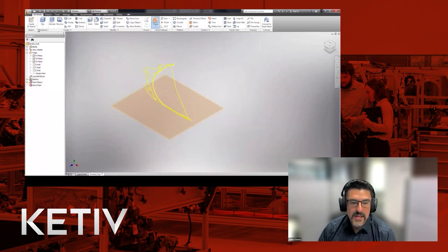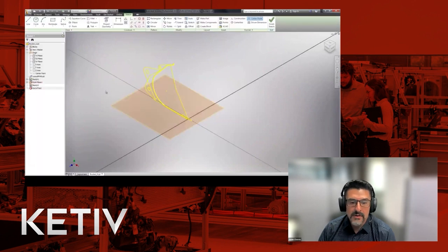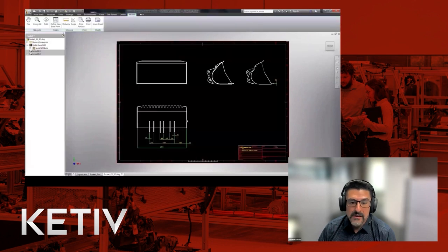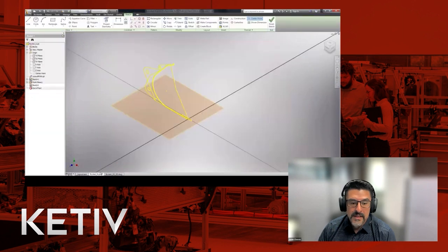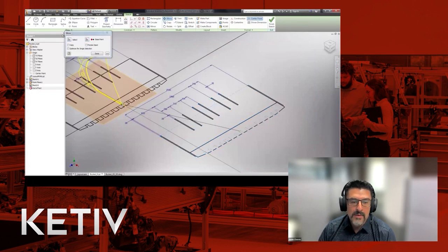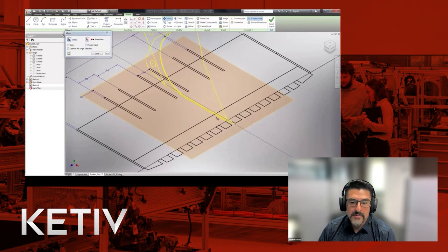So there's already one sketch there that was copied and pasted from AutoCAD. We're creating a brand new sketch. We're opening up AutoCAD directly from Inventor, and when you do that, you can just copy and paste directly. So as we paste it in onto this other plane, it's going to be in the wrong position. And we're going to go ahead and just move it so that, in relationship to each other, there's a common datum point or common point that they both share.